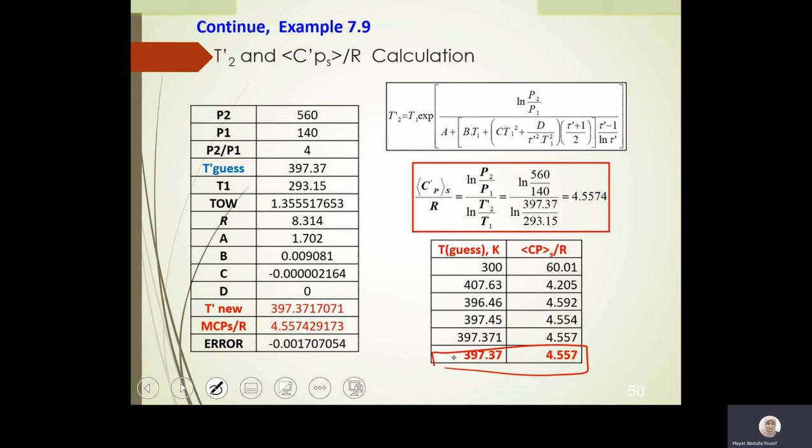This is the first one for the work, this is the second one for delta H, and this is the third one for delta S. So you have three equations, okay? Again, I will repeat. You need three equations with the pump. One is the isentropic work equation, the other one is the actual delta H, the third one is the actual entropy. So what I did here in my calculation, I calculated the isentropic. Then using the efficiency, I calculated the actual.